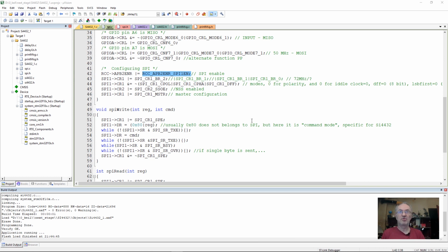Remind me later to also cover so-called bit banging or byte banging, where we do not use hardware. In the hardware case, let's call it a modem, although it's not a modem, the hardware on the microcontroller does everything. We just put data in and the microcontroller sends and receives data, shifting and so on. Bit banging means that we take a byte, separate it bit by bit and bang on the wire. For example, put one byte on one wire and then clock on another.